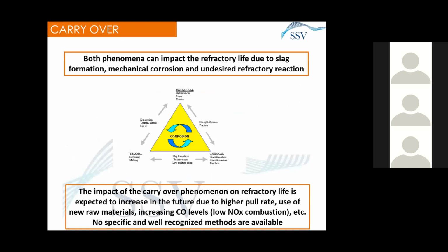One other thing that it's important to take into account when there is a combustion optimization is the carryover. With carryover, I mean the phenomenon where some particles, dust particles deriving from raw material, could leave the furnace unreacted and arrive in the regenerators, and this could lead to mechanical corrosion and so damage the refractory. This affects also the life of the furnace itself.